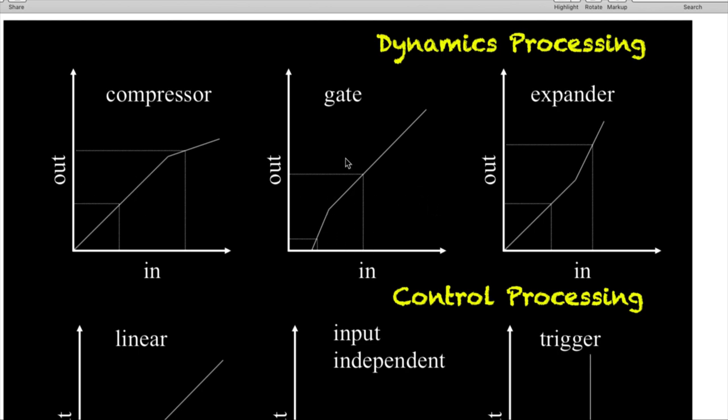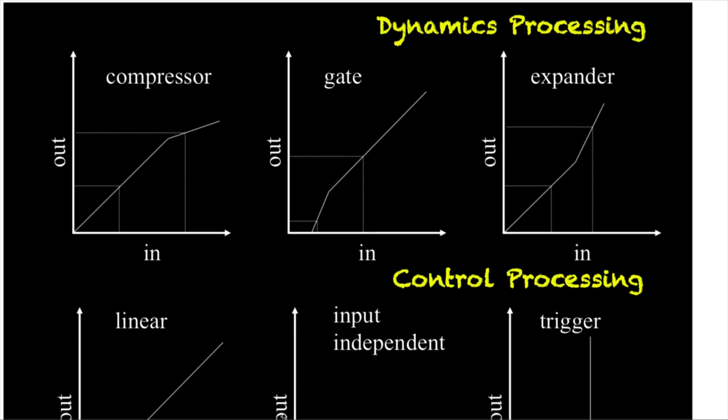Okay, so here is a gate. Typically in audio processing, what a gate does is for very low input values, there is no output at all. So the output is 0 for these values. And then there is a little bit of transition in order to link up to the linear transfer again. So no change in input-output gain here. Here is an upward expander, just a revision really. So we have a linear bit, and then above this threshold, the output becomes louder than what the input was in that fashion.